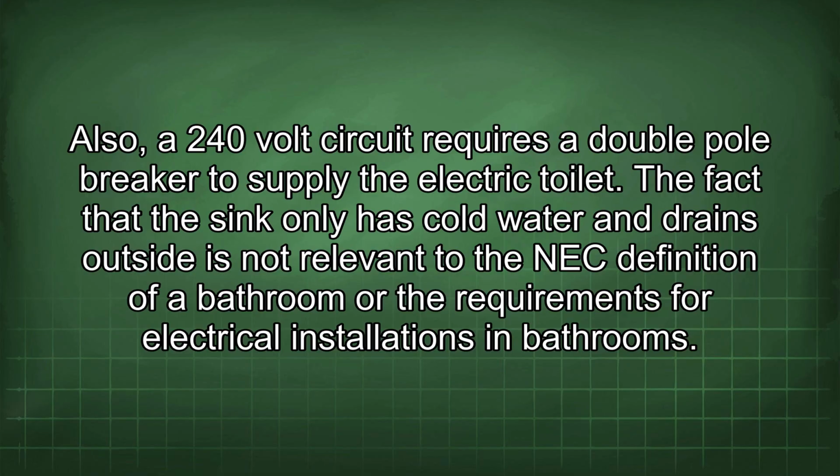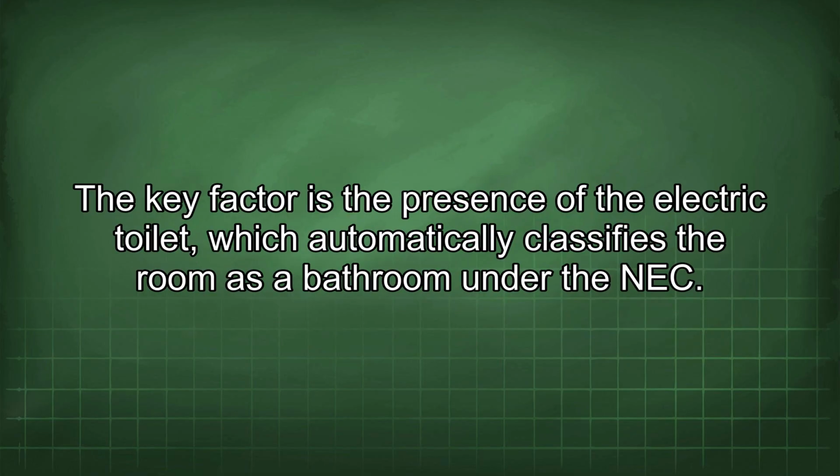The fact that the sink only has cold water and drains outside is not relevant to the NEC definition of a bathroom or the requirements for electrical installations in bathrooms. The key factor is the presence of the electric toilet, which automatically classifies the room as a bathroom under the NEC.